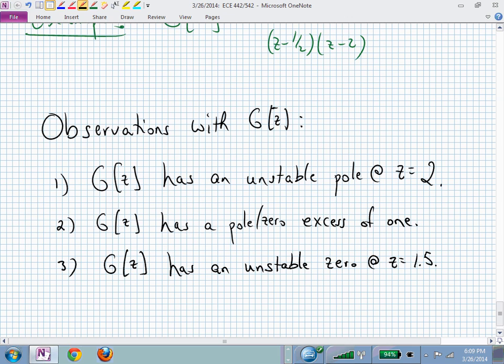So that was a good comment. It doesn't make your system unstable, but if your system is unstable with poles, it makes your job of stabilizing it more difficult. And even if you have a stable system, open loop, and unstable zeros, it makes your control problem more challenging. But it doesn't make your system initially unstable. Maybe that was your question. Thank you.